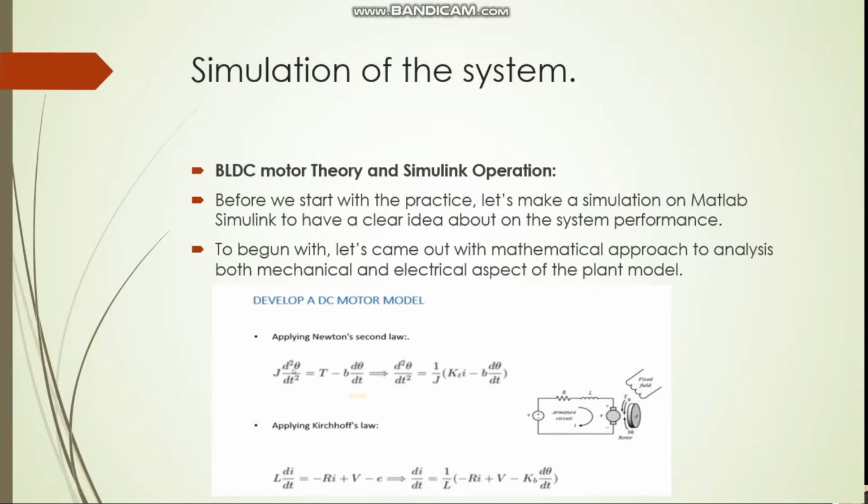First, for a DC motor, think like you have a wire, and you give a power supply to the wire. Once there is power to the wire, a current is created in the wire, and once there is a current, a magnetic field is created around the wire. If you place that wire within a permanent magnet, there will be an interaction between the two magnets. That interaction will try to make a force.